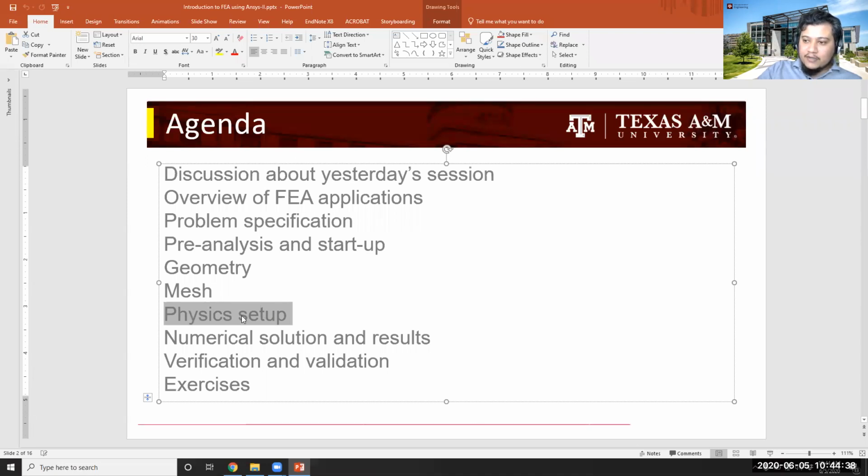So for example, as Hamza asked me a bit earlier, what about the grain orientations? In today's problem, grain orientation is not going to be a concern for us because we are at a much higher scale. But if you were looking at these things at micrometer scale, the grain orientation starts to play a very important role, okay? If I start to play around with isotropic properties at that scale, I am making a huge mistake.